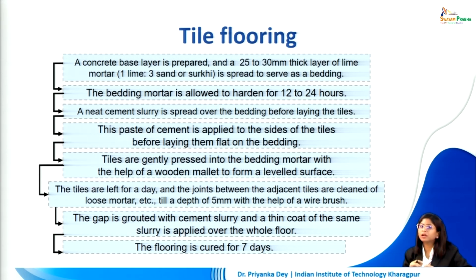And the gap is grouted with cement slurry and a thin coat of the same slurry is applied on the overall floor, so that in case there is any gap, that is covered. The floor is then cured for 7 days before we start use.